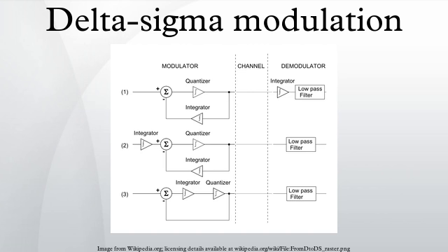Variations: there are many kinds of ADC that use this delta sigma structure. The above analysis focuses on the simplest first-order, two-level, uniform decimation sigma delta ADC. Many ADCs use a second-order 5-level sinc3 sigma delta structure. Second-order and higher-order modulator: the number of integrators, and consequently, the number of feedback loops, indicates the order of the delta-sigma modulator. A second-order delta-sigma modulator is shown in Fig A4. First-order modulators are unconditionally stable, but stability analysis must be performed for higher-order modulators.